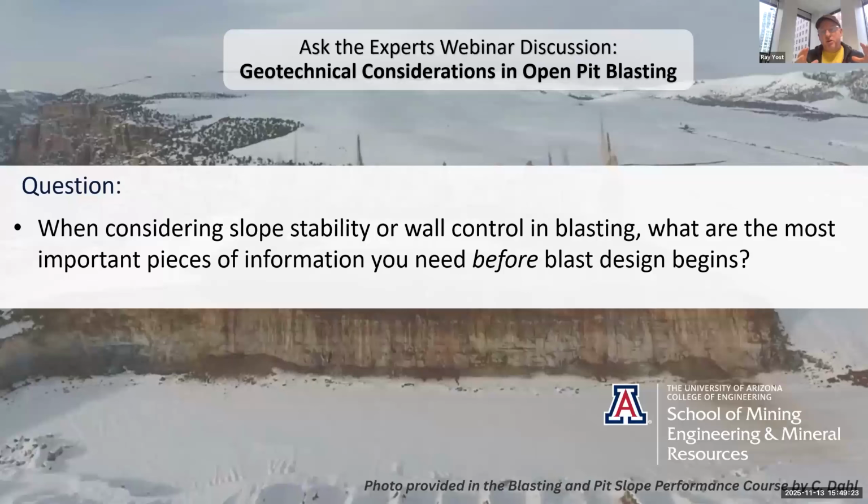Blasting economics, and this is the small scale, economics around the drill and blast costs versus the larger operational economics, considering the crushing and design conformance costs and things like that. So really just, again, to echo some of the previous statements, getting everybody aligned on what is the purpose of that particular blast. And again, it's not going to be the same for every blast. There are going to be parts of the pit, as you shift around, that will have very different trade-offs. And understanding how that shifts as you go and blast in different parts of the pit is of considerable importance as well. So quite a bit to think about even before you get started.